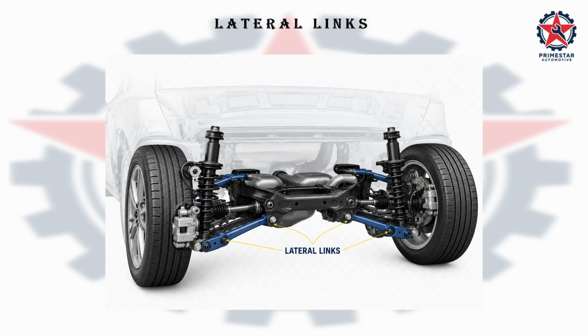Now let's move from the trailing arms to lateral links. Lateral links are commonly found in the independent rear suspension system, also known as IRS. They connect the rear wheel hub or hub carrier to the vehicle's rear subframe. Their main purpose is to keep the wheel correctly positioned while still allowing it to move up and down independently. In this illustration, the lateral links are highlighted in blue.